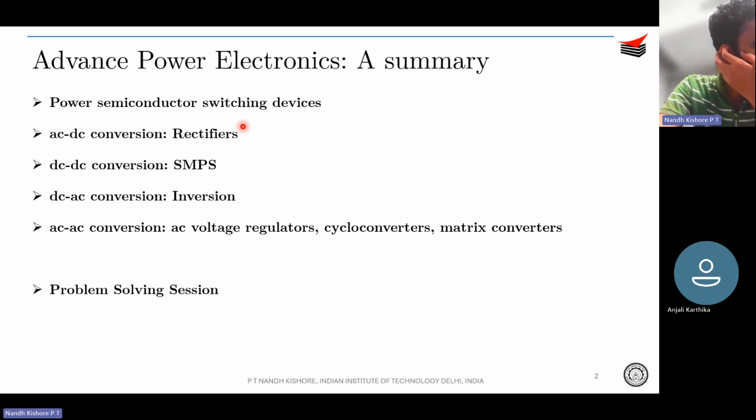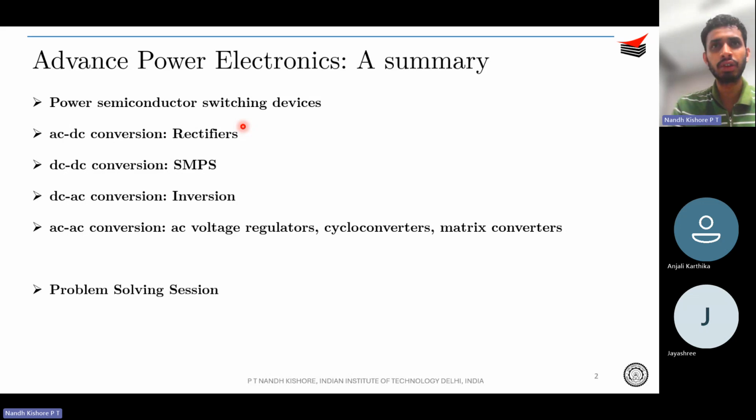Again, you went to half bridge, then full bridge, and then of course the three phase topologies. You studied the 120-degree conduction mode and the 180-degree conduction mode. You also studied different PWM techniques: unipolar PWM, bipolar, sinusoidal PWM, uniform PWM, and then a bit of space vector modulation, including third harmonic addition. So this was about inverters: topologies as well as some PWM techniques.